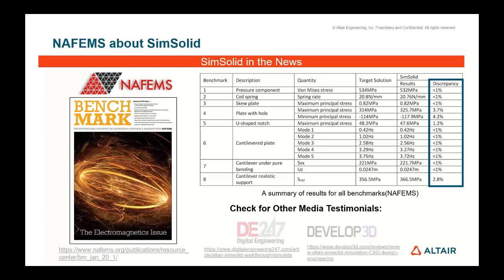I would say no. We can just import and start calculating, because upon import, all the different parts will be connected automatically by SimSolid. Yeah, pretty much. There's an auto contact feature on importing. You can define an automatic tolerance. Like Jan said, there's an auto contact feature, so you don't need to worry about having to define constraints for individual parts.